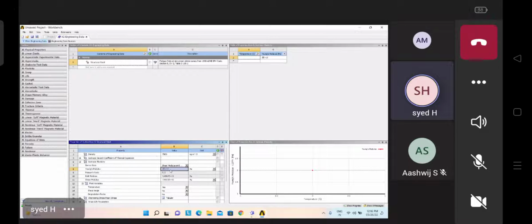But most of the time these values remain constant here. Why? Because under the elastic limit those values remain constant. So like that we can enter the values here and edit our property. The next thing is how to call new materials. Here you can find only one property, that is structural steel. What about the remaining materials?